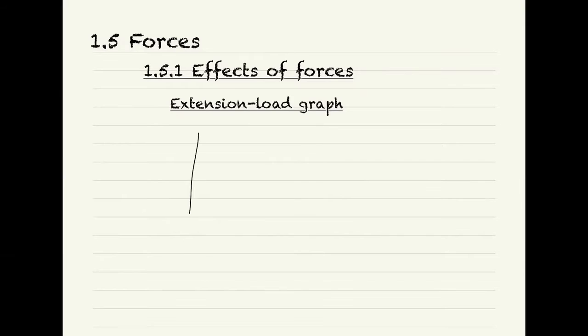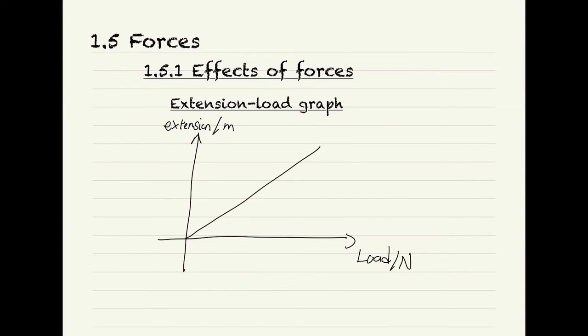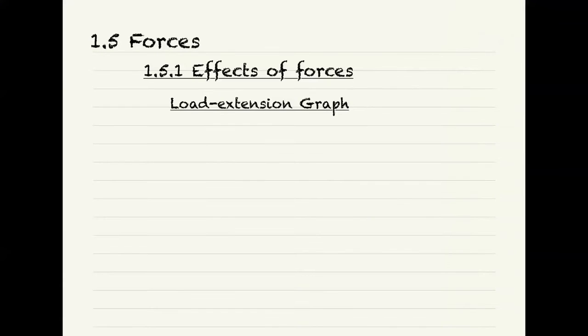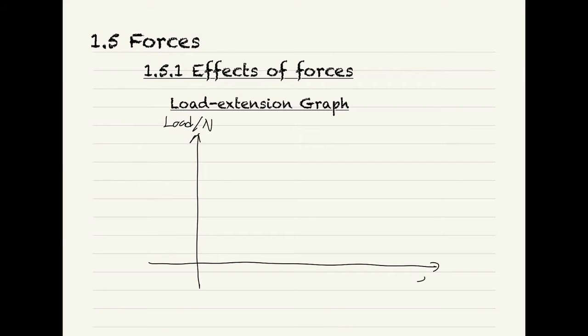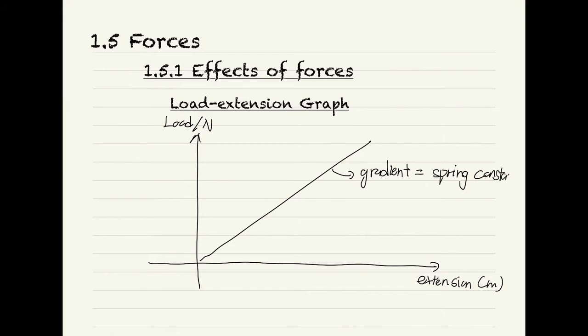From the extension load graph, extension against load, gradient will be equivalent to 1 over spring constant. For the load extension graph, load against extension, gradient will be equivalent to spring constant with the unit Newton per meter.